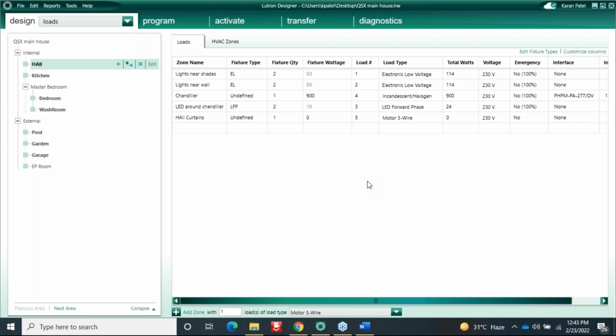And if I'm controlling something on the motor module, tell me, what should the load type be on the motor module? If I'm controlling a third-party motor module, or whatever we are connecting to the motor module, it should be motor three wires. Motor 3 wire, so very good.